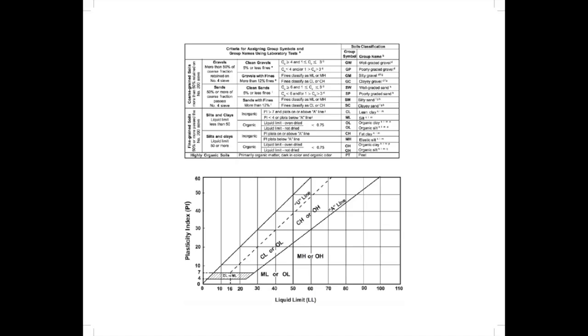From the geological reports, we are given information about the grain size distribution and Atterberg limits. With this, we are able to classify the soil by two methods. We can classify the soil by the USCS ASTM standards and the AASHTO specifications. First, we will classify the soil by the ASTM standards.